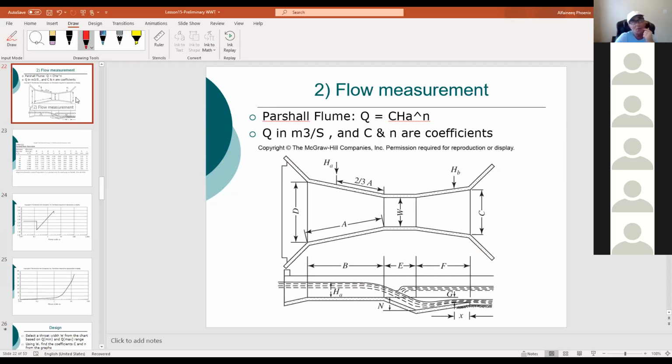Yes. All right, now the water comes from this pumping, goes to the settling well, then it starts running in an open channel, concrete open channel, right? And the first thing you need to do is to measure that flow because it has debris and different things still in it. The best flow meter is the Parshall flume.